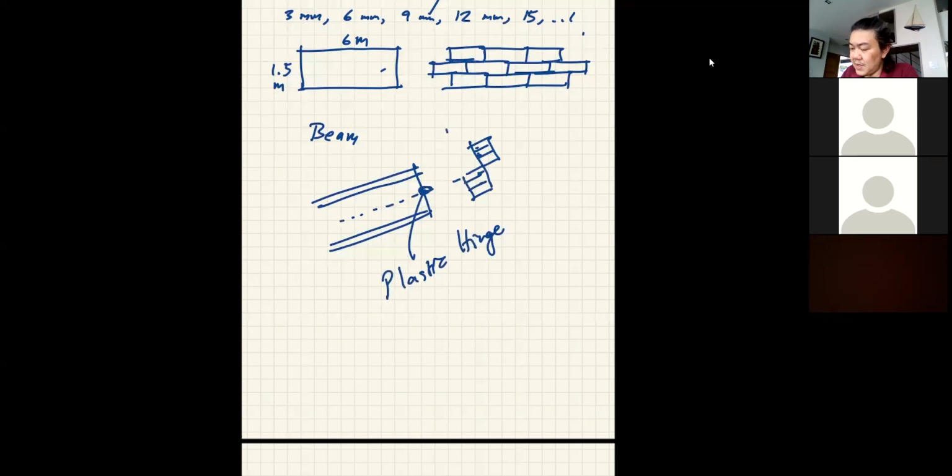This is the plastic stress distribution, which leads to the plastic section modulus of the section, the Z. Okay, and we also mentioned yesterday that the Z in the typical catalog is unfortunately the elastic section modulus, but Z in my table, that's plastic.